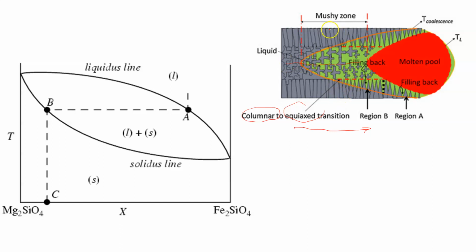And what you're seeing up here is just defining the entire mushy zone of the metal. So this means that you're still cooling down and you're in the recrystallization. So the crystal is actually growing. So you can see you've got the entire phase diagram happening here. So this could also be called recrystallization. So you've got all sorts of different phases of the phase diagram, both within the electrode region and following behind where the crystals actually start to reform.